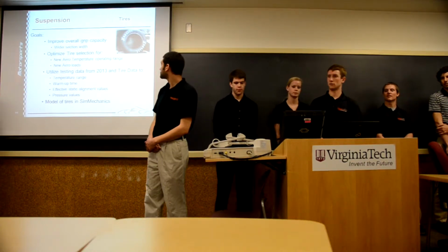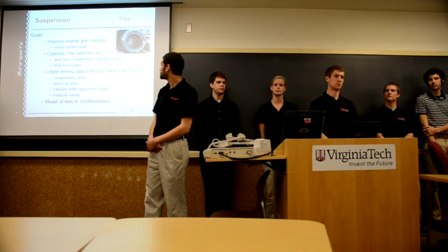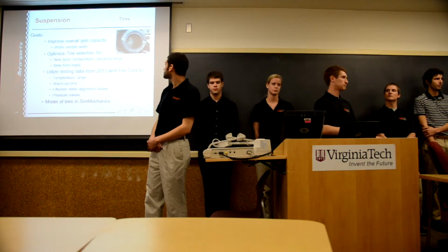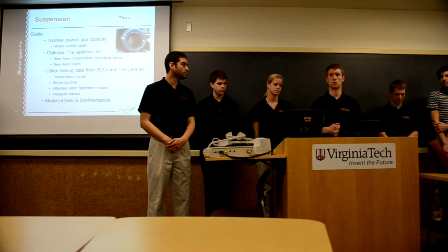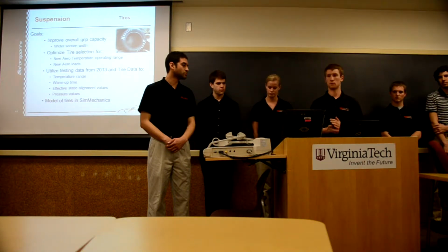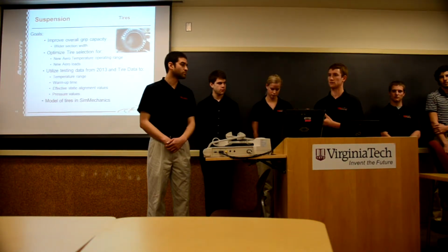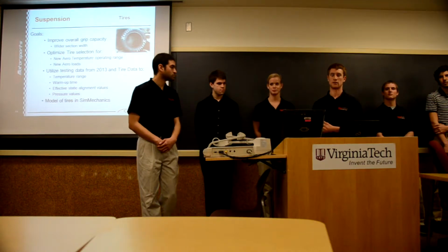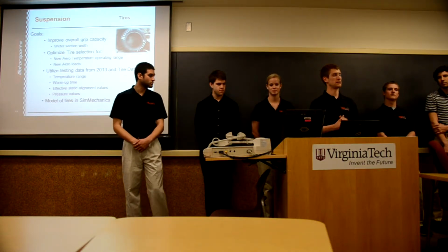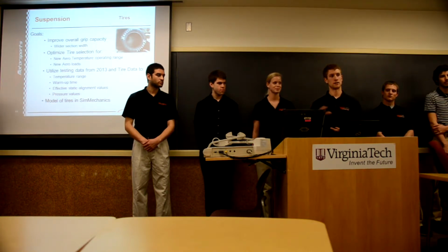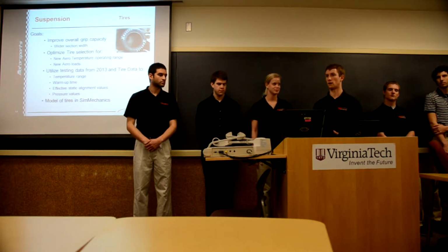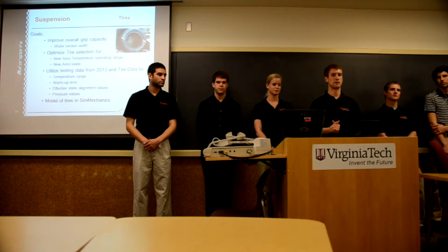All right, so for 2014, I'm continuing my work on 2013. We're going to probably upgrade to a new tire package. Preferably, I'm looking to go to a wider tire. Hopefully here we'll upgrade our overall total capacity for lateral acceleration. So what we're doing is optimizing the tire selection for the new aero loads. These are going to change our temperature ranges, possibly our warm-up times, so we choose a compound that's apt to that.